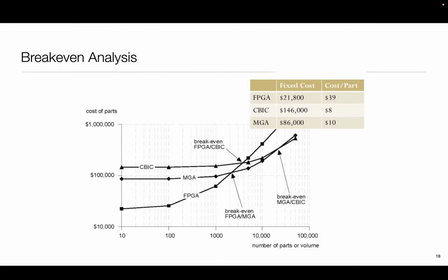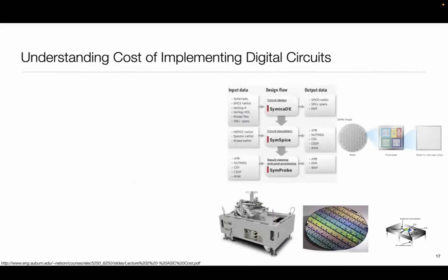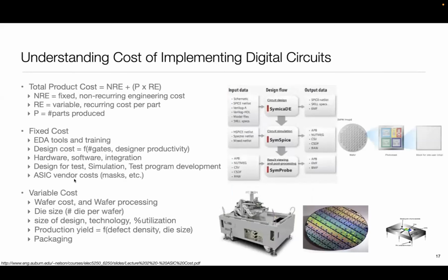So let's think of, let's say I'm making a processor. A processor is very costly. Intel processors can run into many thousands of dollars. But if I'm making only a few systems, then it's better for me to use those, assuming speed was acceptable, than designing my own ASIC, because then I will take the cost of all that mask making and non-recurring cost on my own.